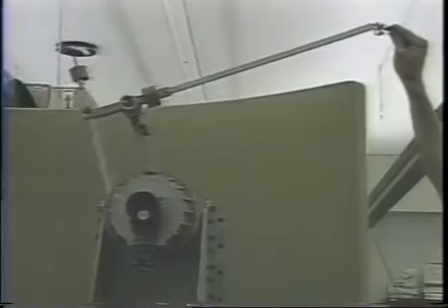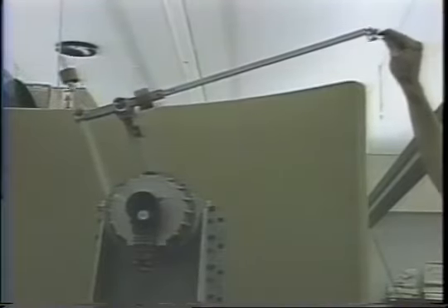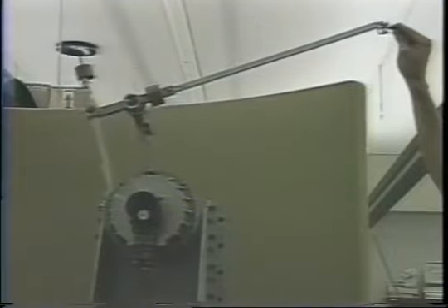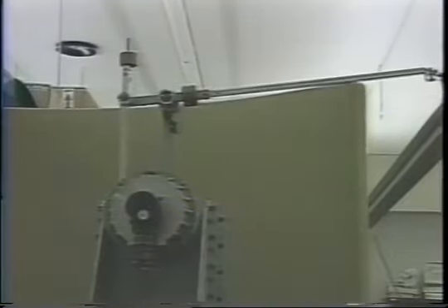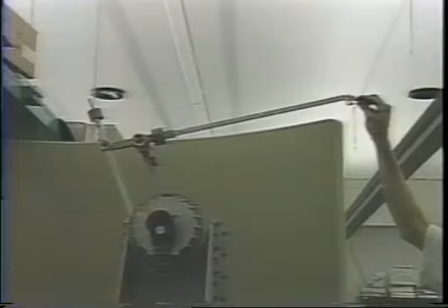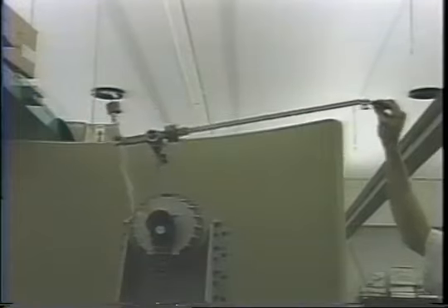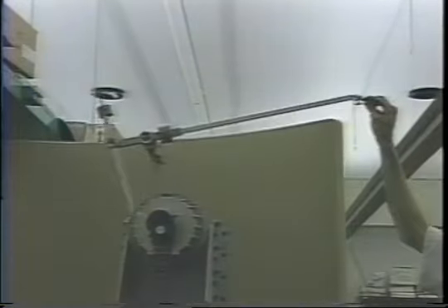When an implicit force controller is used and the stiffness of the virtual wall is increased, instability can result when the user attempts to touch the wall with a constant force. Recently developed techniques have shown that the instability can be reduced to a great extent by the use of a switching control strategy.